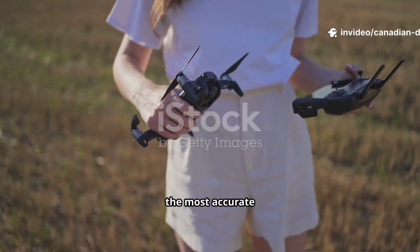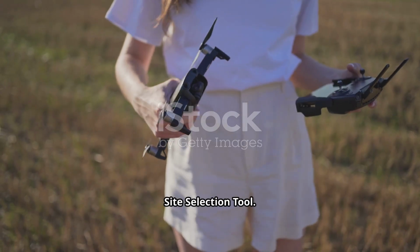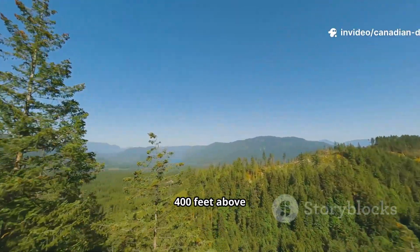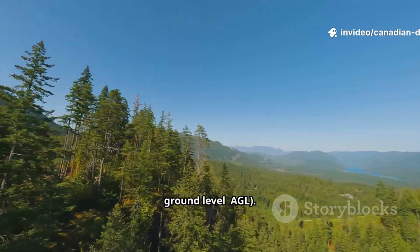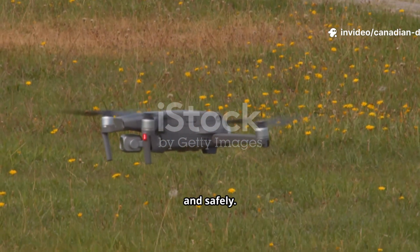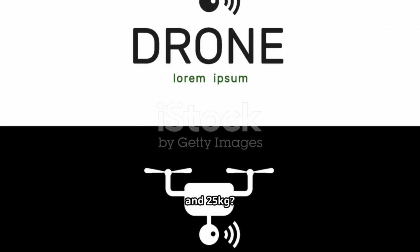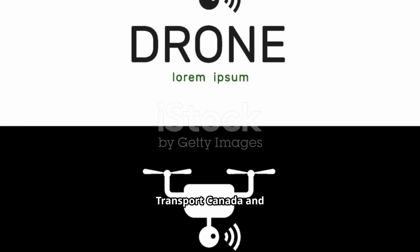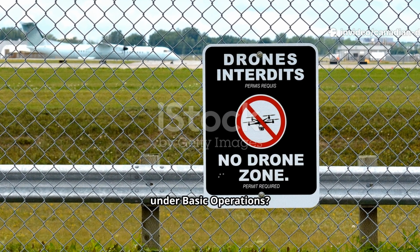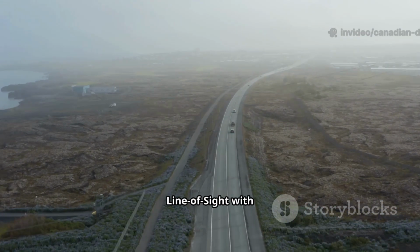Where can you find the most accurate information on airspace restrictions? NAV Canada's drone site selection tool. What is the maximum altitude you can fly your drone? 400 feet above ground level, AGL. You are flying in a park and hear a helicopter approaching. Land immediately and safely. What must you do before flying a drone between 250 g and 25 kilograms? Register it with Transport Canada and mark the number on the drone. Can you fly over a crowd of people under basic operations? No. What does VLOS mean? Maintaining visual line of sight with your drone.